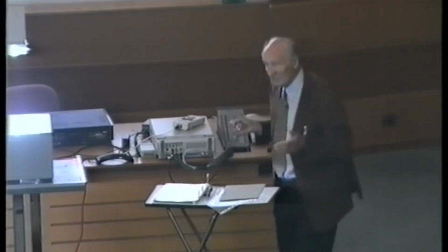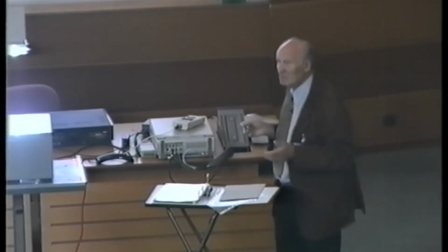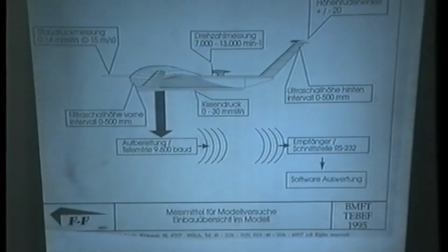When we have a constant flight with constant speed, the drag is the same as the thrust, and we can directly say what is the lift to drag. And we find immediately any modification, whether it is good or not good, and what the results are. These models are built in a ratio of 1:16 under the model rules. You are familiar with these scale rules. Otherwise you cannot make a prediction of what's coming out.